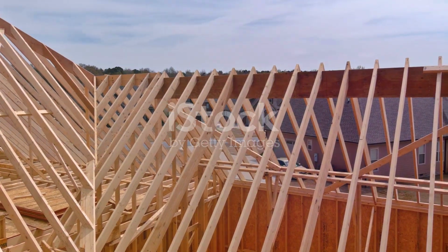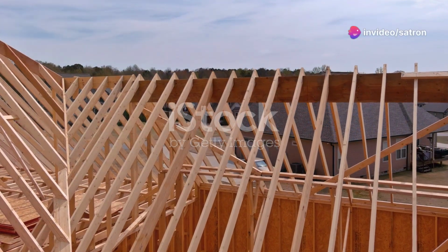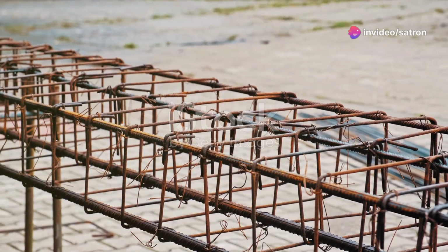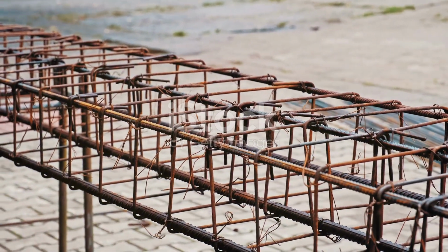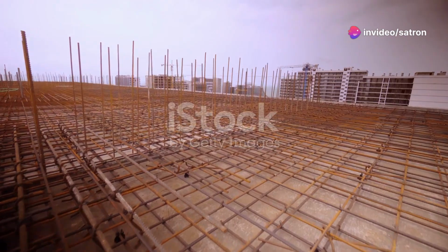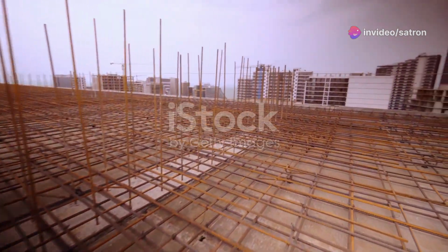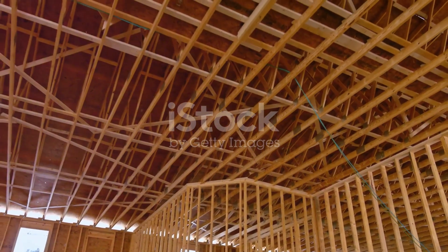But here's the cool part. Once the concrete hardens, the steel decking doesn't just go into retirement. It actually works together with the concrete, forming a composite system that's stronger and stiffer than either material alone. The corrugations in the steel decking create a mechanical interlock with the concrete, preventing slippage and ensuring that the two materials act as a single unit. This composite action allows for longer spans, reduced concrete thickness, and improved fire resistance.